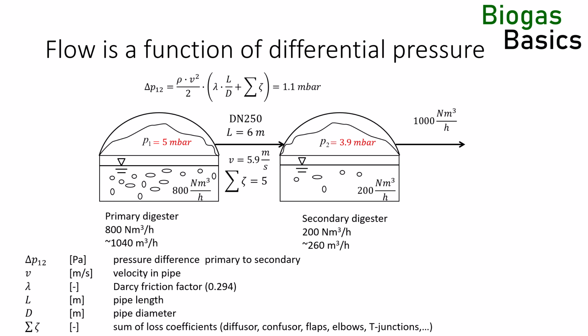When a gas dome is either full or empty, its inner membrane will lay itself onto the outer membrane or the belt structure, and the restriction will take up some of the area force and allow the pressure in the biogas space to deviate from the pressure set up by the blower and pressure control flap. If the gas dome is full, the outer membrane projects a force onto the inner membrane and the biogas space can be overpressurized to provide a sufficient pressure gradient to push all the gas produced in the digester downstream.